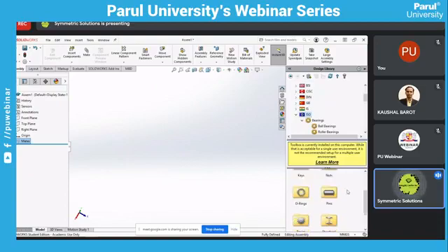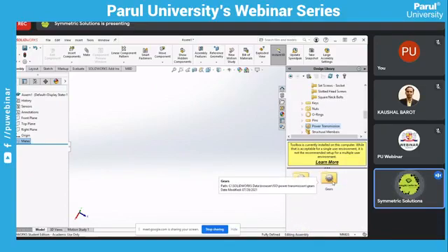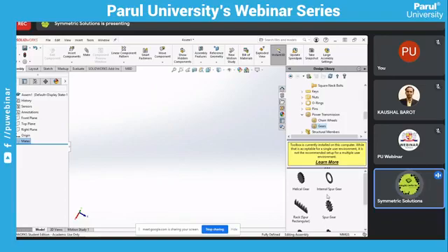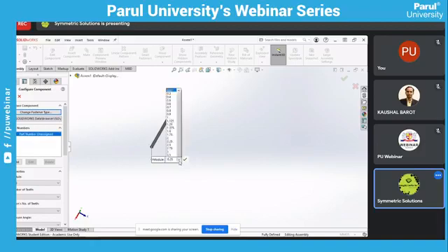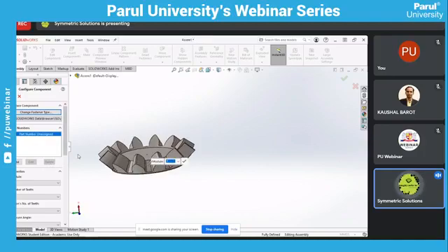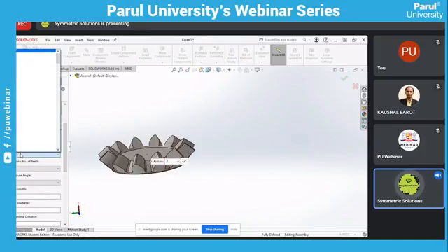In power transmission, we have some gears as well as chain wheels. In gears, we have helical gears, internal spur gears, bevel gears, straight bevel gears as well as straight bevel pinion gears. If we need some bevel gear, just drag and drop. Select your module size, and define module size as well as number of teeth. How many teeth do you need? We need 30.